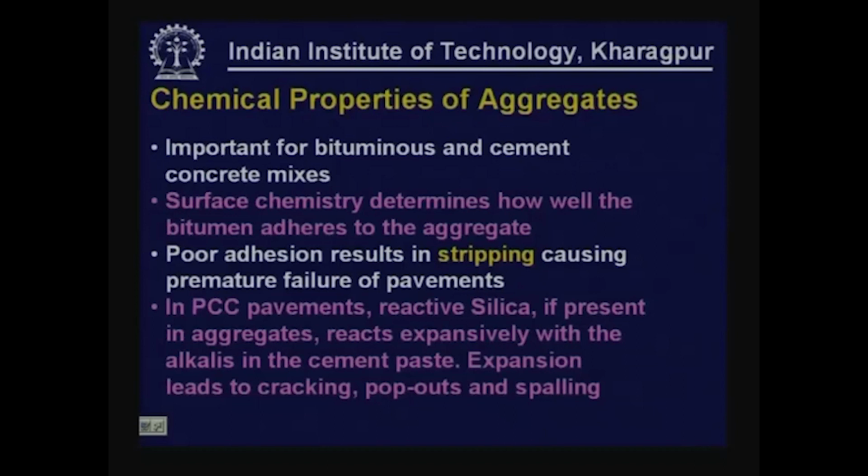This has been a very common failure occurring in several flexible pavements. So, this is a very serious failure. We should be concerned about the surface chemistry of these aggregates and also the adhesion between bitumen and the aggregates. In PCC pavements, we are concerned about the presence of reactive silica.